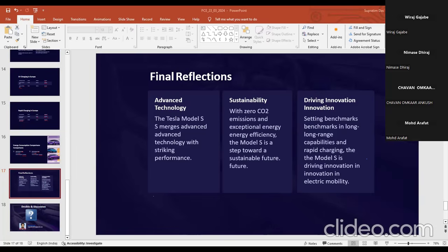You should consider your vehicle parameters: the vehicle mass, the vehicle shape, how much air drag coefficient or CD value you are expecting, how much frontal area your vehicle has, the rolling resistance coefficient based on the tires and the road surface, and also the wheel radius. If you have these parameters, you can select your powertrain and also calculate the consumption for a certain range you are expecting out of the vehicle.